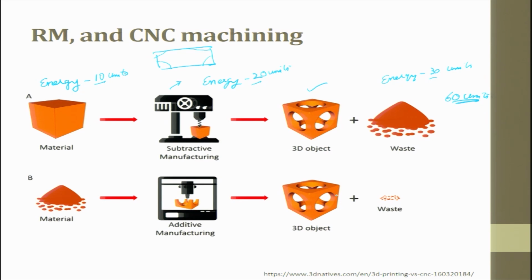To do this in a conventional machine, first of all I have to take the part, and then I plane or I mill all the four sides. If it is large I plane, or if it is small I mill. Or if it is in between, then we use a shaping operation. We try to make flat faces, and making flat faces also you have to do on all 1, 2, 3, 4, 5 and 6.